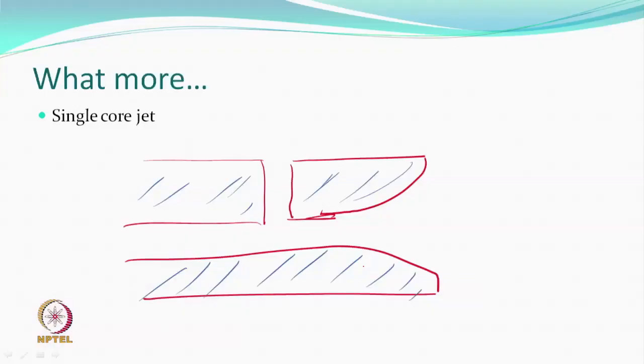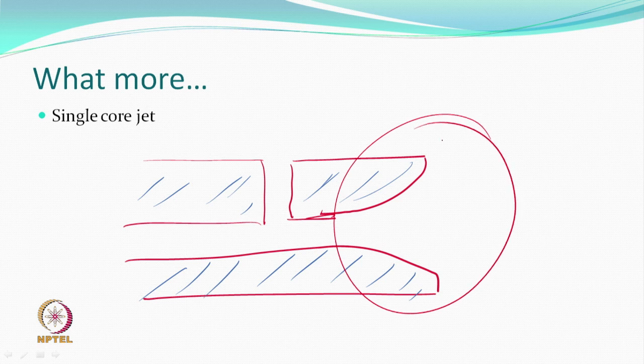by more pressure, more nozzles. Higher denier, more nozzles; lesser denier, single nozzle, and expand in a trumpet shape. Why trumpet? Why this kind of a shape instead of the other one? It is again controlling the decrease in pressure, but no serious reasons available except, well, the other conical things were all patented, all angles. So, you got to have something else.